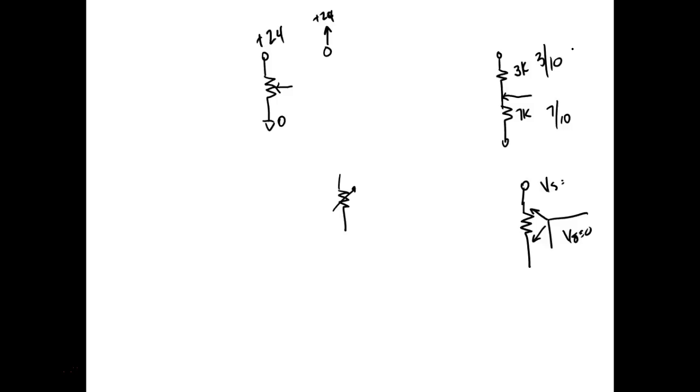But I could literally set anything I wanted to, right? You understand? If we use what we call a linear taper pot. And of course, I could calculate the voltage that I would get out of here. Now, the problem is when I bring this into the analog input of my PLC, what it's going to look for is from 0 to 10 volts. So it's got two ranges you can set up: 0 to 10 volts or 0 to 5 volts. Allen Bradley doesn't give you the ability to set the range. It's either 0 to 10 volts or nothing.